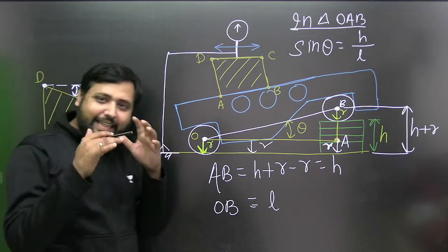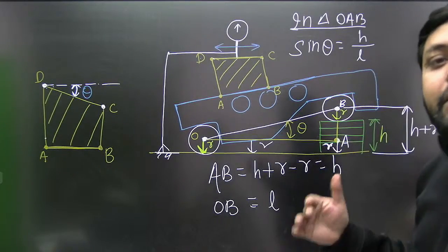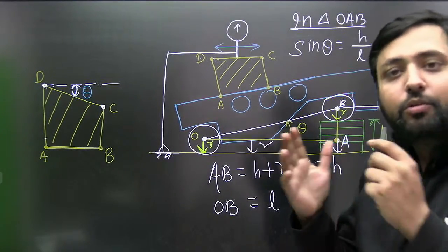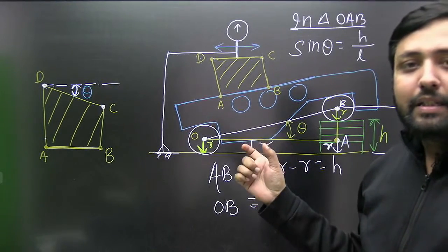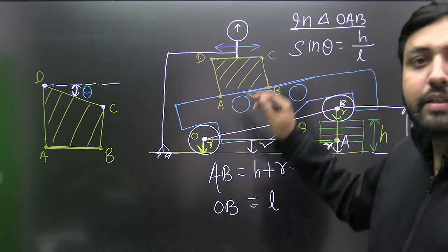But there is a catch over here. You know, we don't and we can't and we should not measure any angle above 45 degrees with the help of a sine bar.